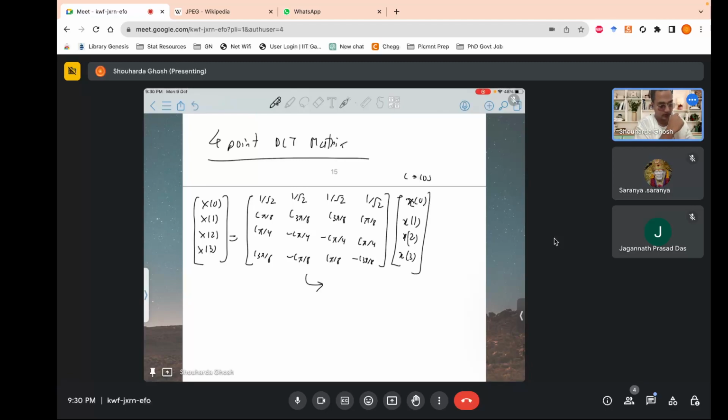so you see there are only n minus 1 equal to 3 true coefficients. Let me write it down as c1 hat, c2 hat and c3 hat, where c1 hat is cos pi by 8, c2 hat is cos pi by 4 which is 1 upon root 2, and c3 hat is cos 3 pi by 8. Okay, so now I shall move into the architecture.